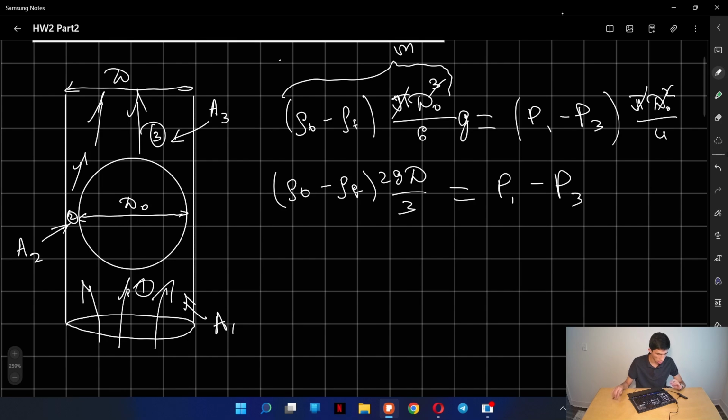Okay. And if we look at our diagram, we can see that the cross-sectional area at point 2 is very small, right? And when it goes to the cross-sectional area at point 3, we're considering it to be a sudden expansion problem. So when the flow is going from point 2 to point 3, it is experiencing a sudden expansion, which means there is no pressure recovery.